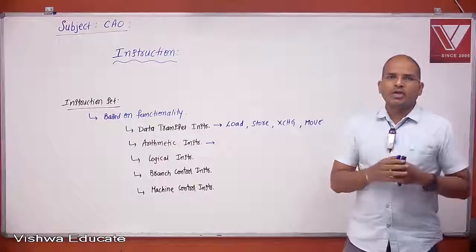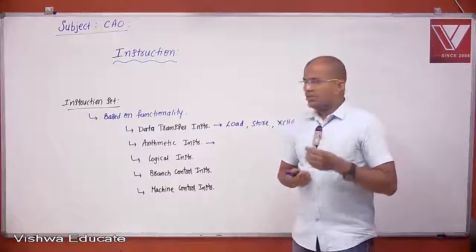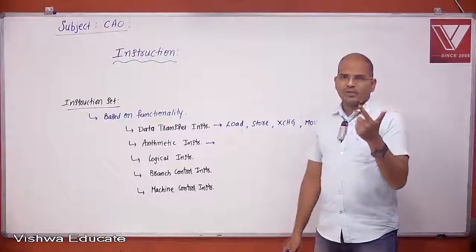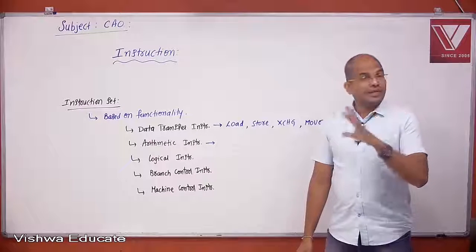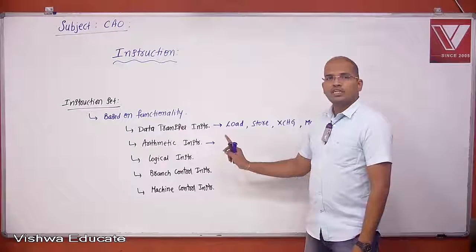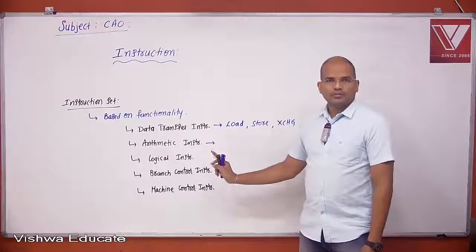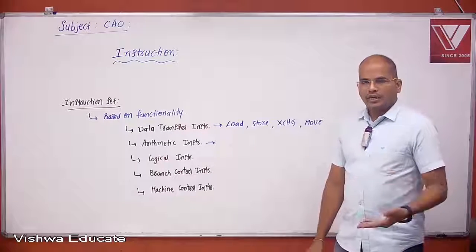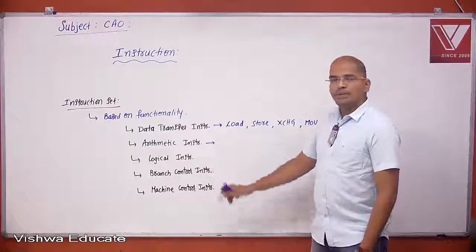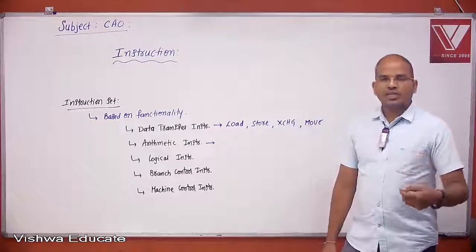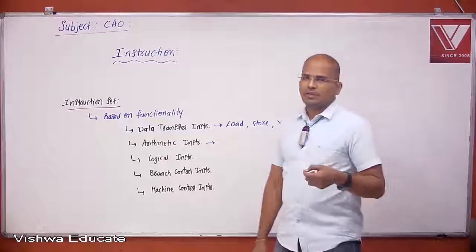For example, your 8085 microprocessor supports addition, subtraction, increment, decrement. It does not support multiplication and division directly. Then we should perform multiplication as repeated addition and division as repeated subtraction.